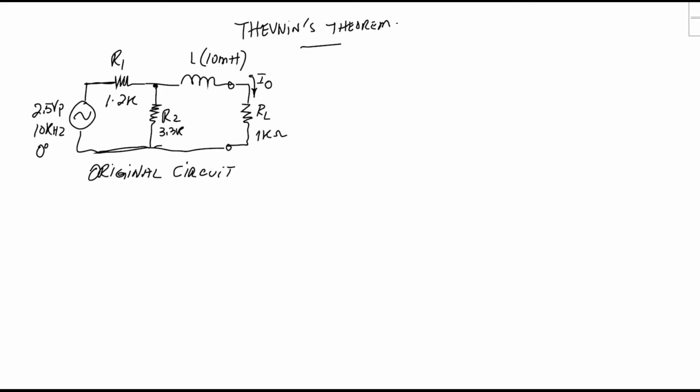Okay. To do this, we do it practically. We connect the circuit as it is, with our oscilloscope, the Tektronix, the one we have. We connect channel 1 to this point here in order to display our V input sine wave, and channel 2 at this point, where we can display V across RL.